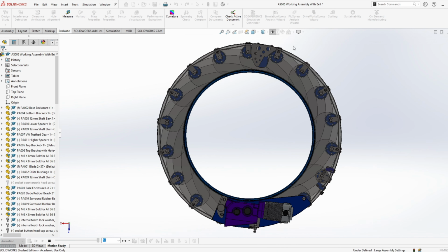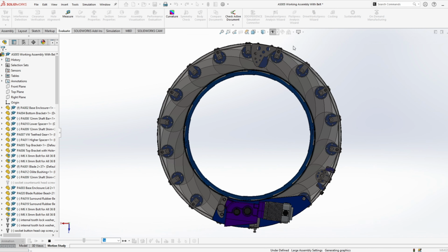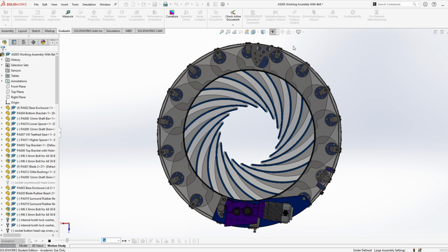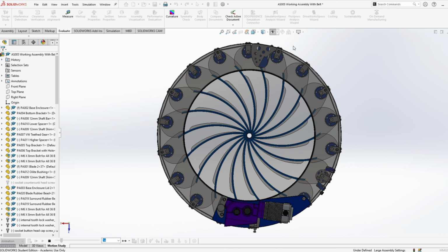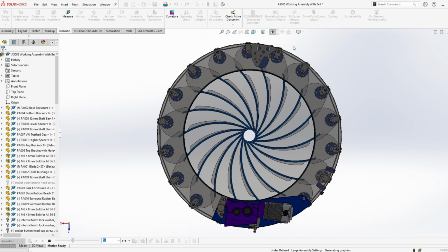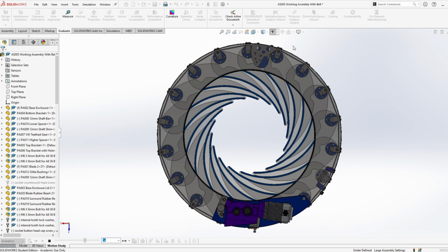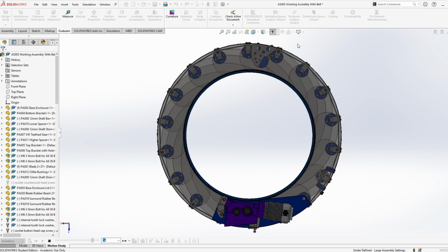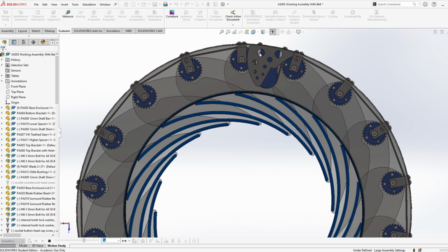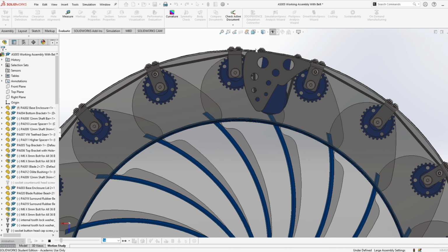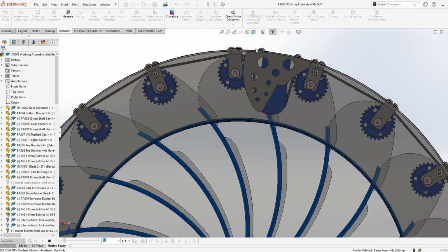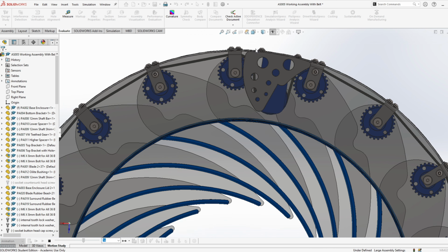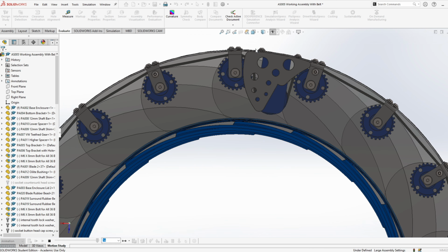If we think about this for a second, this benefits the system in other ways. It balances out the tension of the timing system. For example, if this tensioner wasn't here, the timing system would depend on the tension created on the belt from the gearbox side, which is further away.